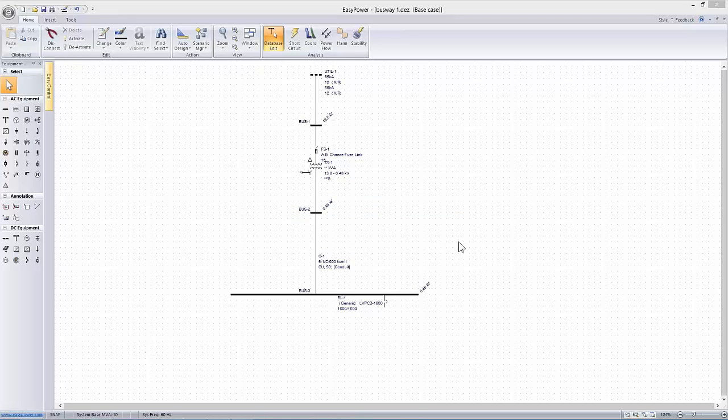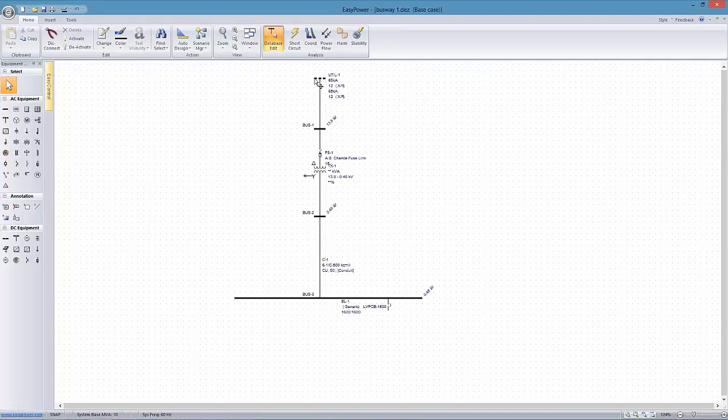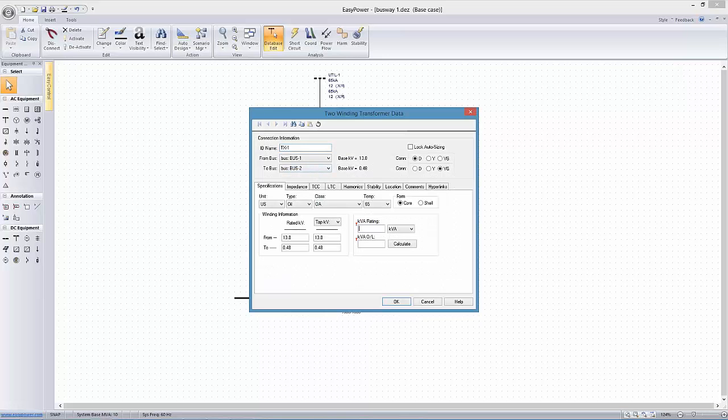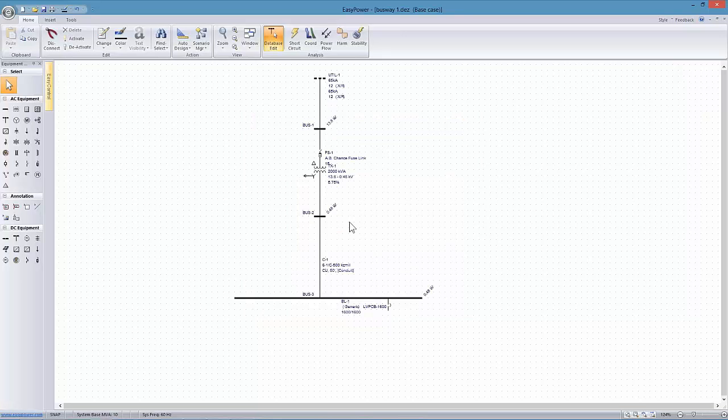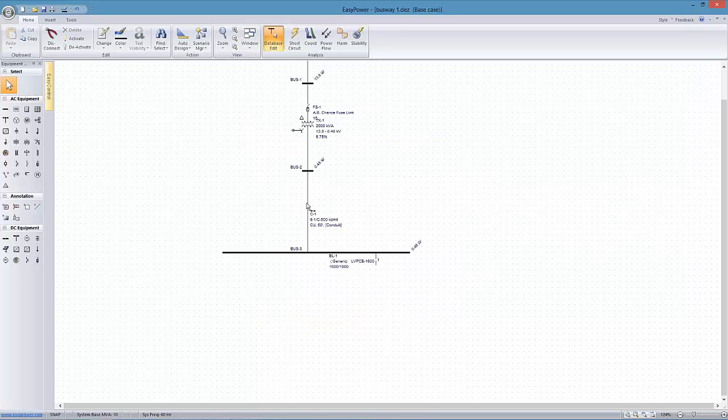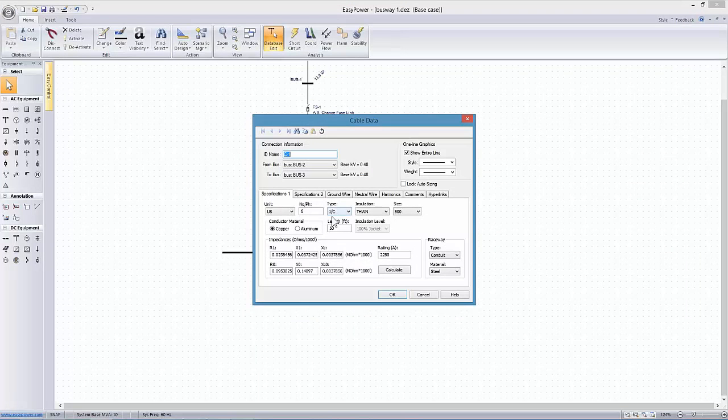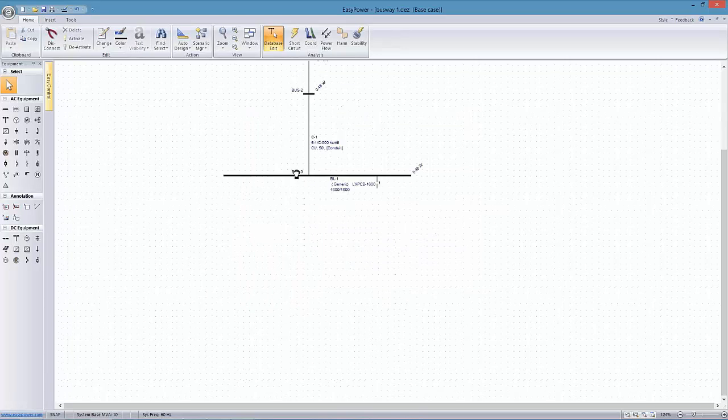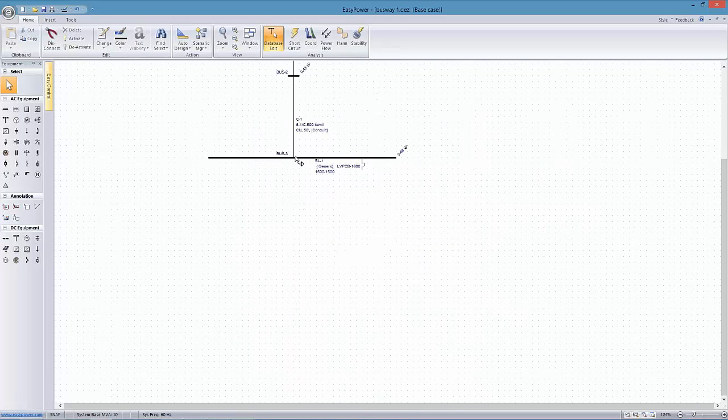All right, so what I'm going to do here is start off with a typical utility installation. I'm using my basic utility cutout fuse. Let's go ahead and put in a fairly good sized transformer. And this is all generic stuff. And then I've connected some cable runs with about a 2200 amp capacity going from the utility to my first switchgear. And from there I want to run my busway.